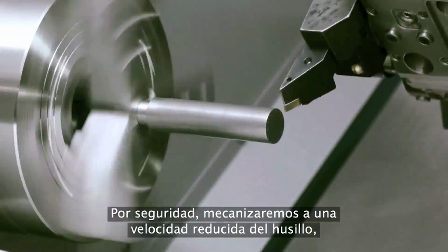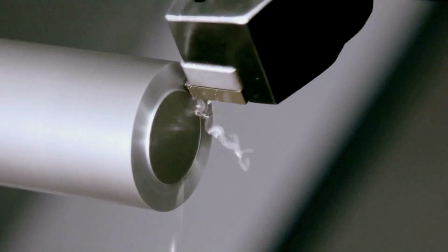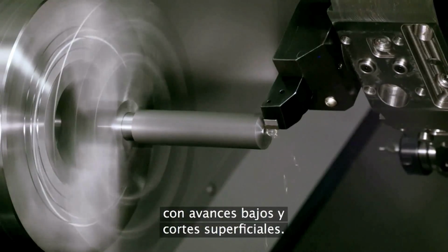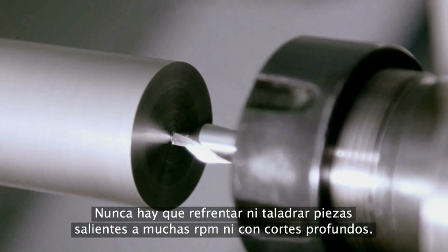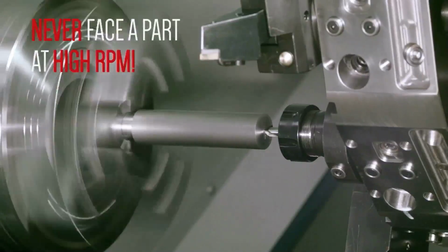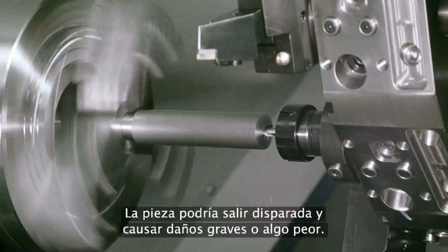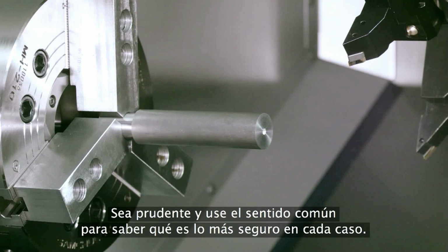For safety, the facing and drilling should be run at slower spindle speeds, with a slow feed rate and a shallow depth of cut, so the shaft won't whip or bend. An extended part should never be faced and drilled at high RPM or cutting loads. The part can be thrown and cause damage, injury, or worse. Exercise caution and common sense when deciding what's safe for your setup.